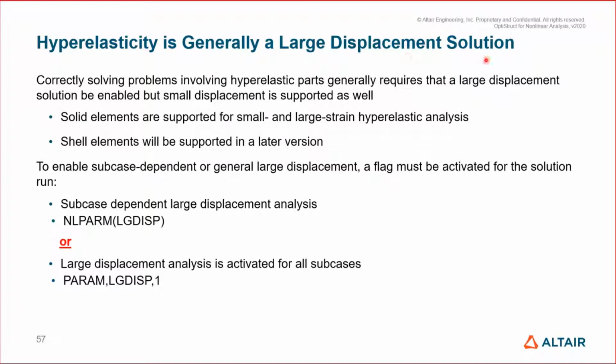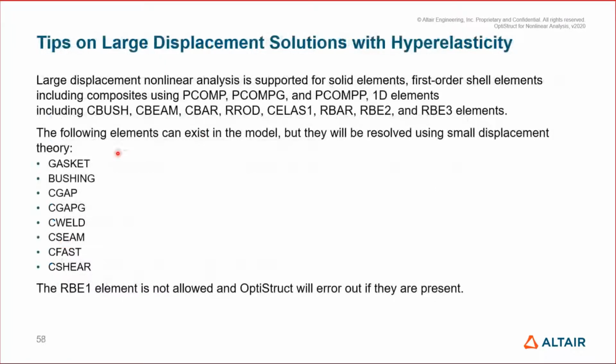Because hyperelastic is a large displacement problem, always remember to turn on large displacement, whether through the PARAM or through the NLPARM. Now, tips on large displacement: all these are supported for large displacement. These other elements can exist in the model, and it won't fail if you turn on large displacement, but all these elements are going to be solved with the small displacement formulation. So we don't really consider large displacement for those elements, but all these here are supported.